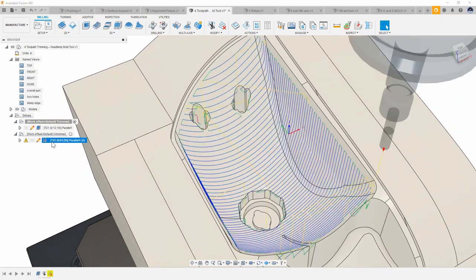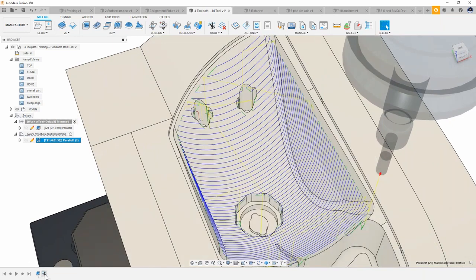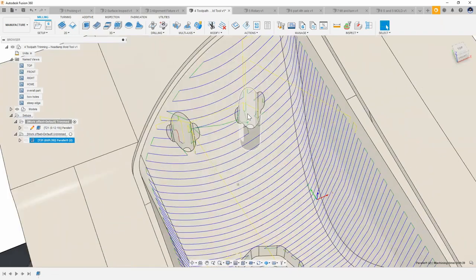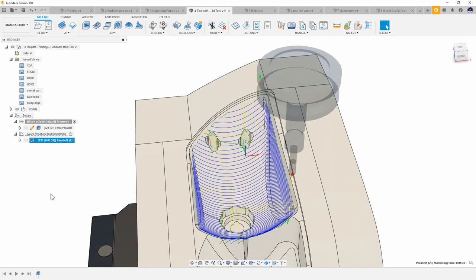And what we can see here is when I grab this, we can see that down in the timeline here, I have some of those features. So this one here looks like there's an error because maybe I selected some passes that are no longer there. We could right click on this and we could easily say delete. And if we didn't like the other edit and we wanted to see the original, we could also click the original edit and hit delete. And then it will produce the toolpath how it was originally without those edits. So these edits maintain associativity and we have a history of them.